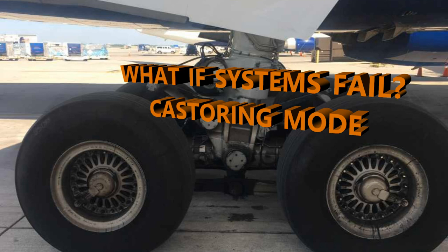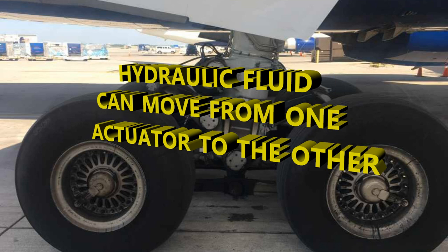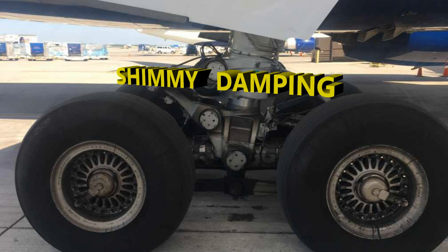There's a pressure kept by an accumulator and also a return check valve, and that's there to prevent cavitation in the actuator chambers, just keeping that equilibrium going. Hydraulic fluid can also move from one actuator to another. Remember I said there's two actuators. There's also an anti-shimmy damping function that's part of all of this.